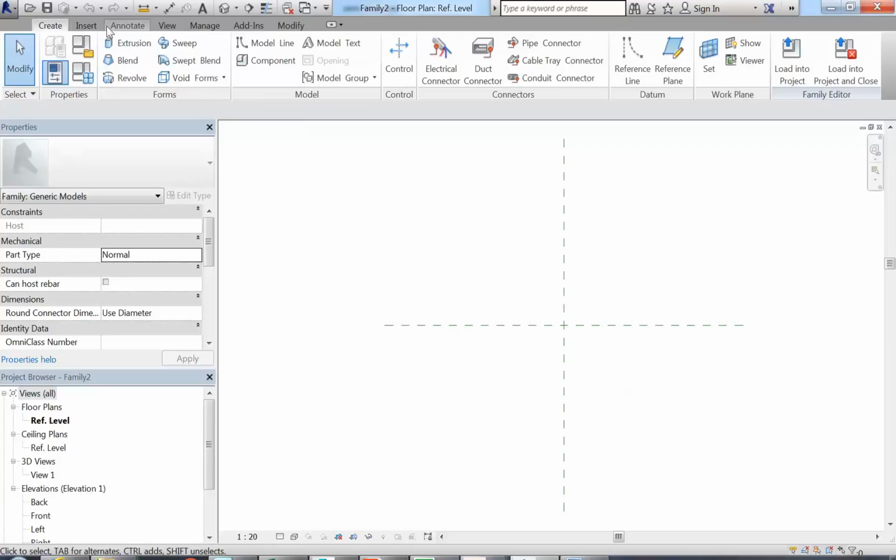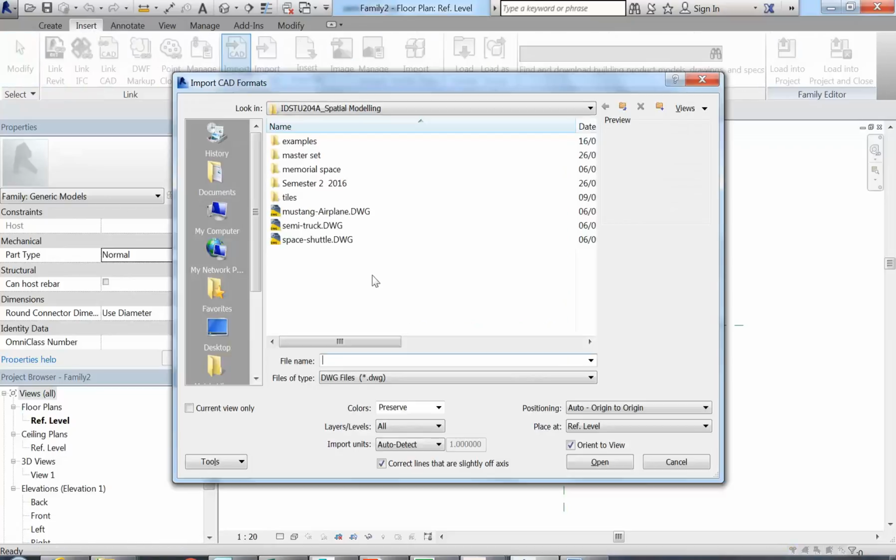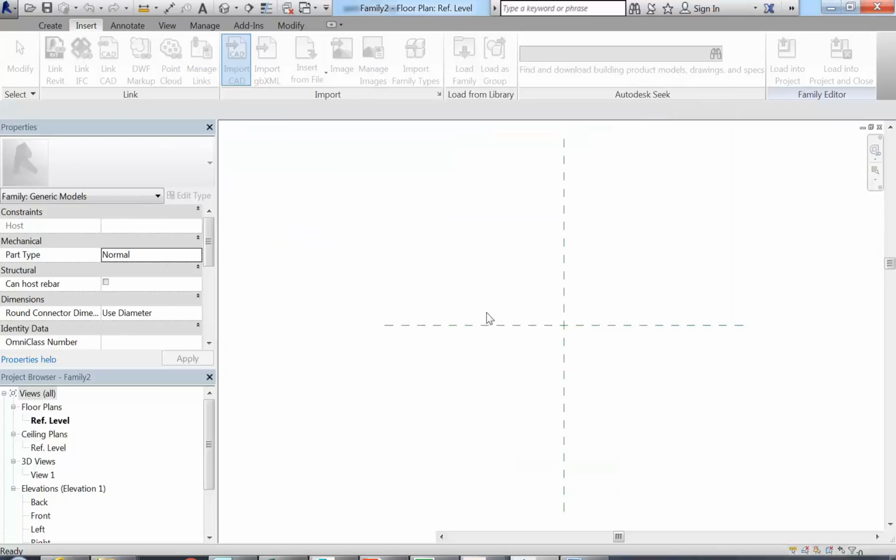And then import your CAD models into that. Okay, so this will work for all kinds of things, furniture particularly. So if you find those chairs on the Knoll website, I think some of them are in Revit, but a lot of them aren't, and a lot of other furniture you'll find is 3ds format or AutoCAD 3D. You can use this to get them into Revit.